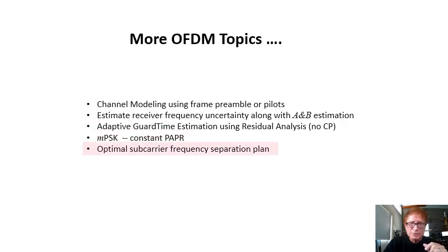Lastly, we have noticed some interesting variation in the estimation convergence for the lower subcarriers. That is, the carriers do not all converge at the same rate. This suggests that there may be a better non-equal frequency spacing that can offer even further symbol time reduction, at least for some subcarriers. We want to take a look at using pairs of closely spaced frequencies, with each pair separated from its neighbor by a larger frequency.